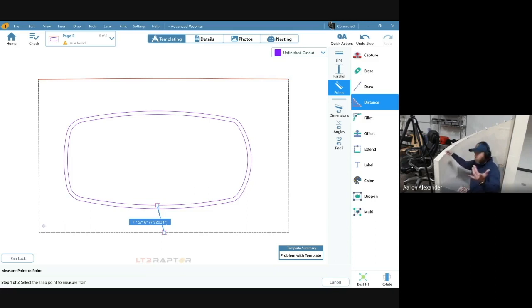Point number 2, point 16, and point 30. And that'll give me a perfectly consistent radius arc that we're going to cut for the cap, because that better be smooth and that better be consistent, right? But we can use the wall to get it. Now, by drawing that off of 2, 15, and 30, you'll see how close that consistent smooth radius matches the scribe.